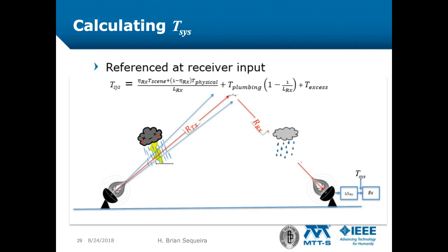The receiver must accumulate sufficient signal energy within the permitted detection time to satisfy probability of detection and probability of false alarm for a specified target size at a given maximum range. To do this, the transmitter must direct sufficient energy at the target within that time, or in other words, transmit power at the target. We consider an example in the following slide.